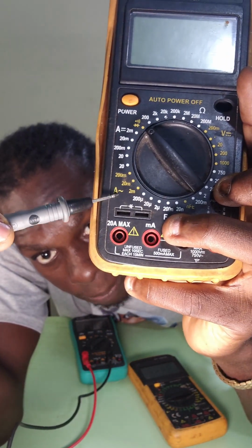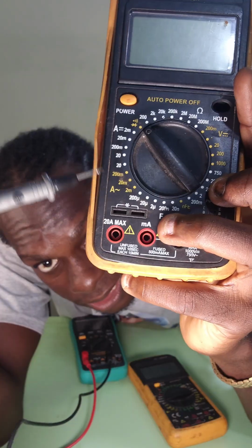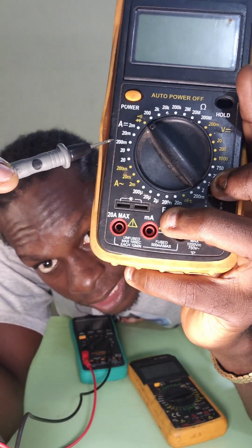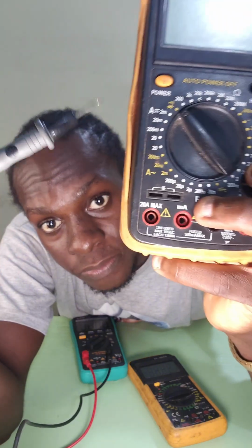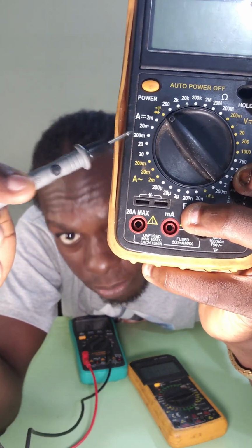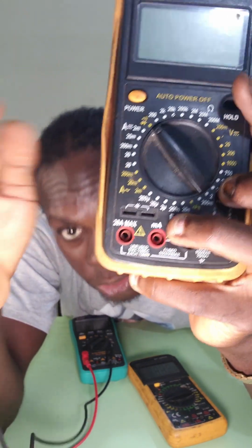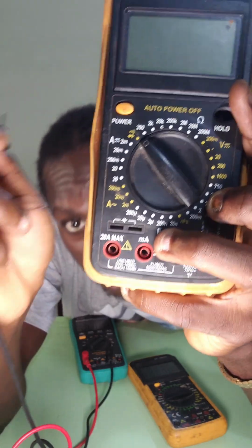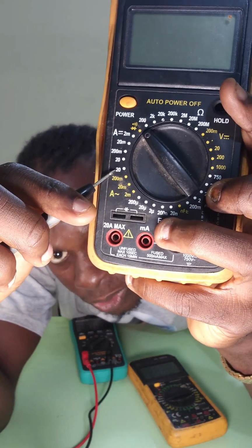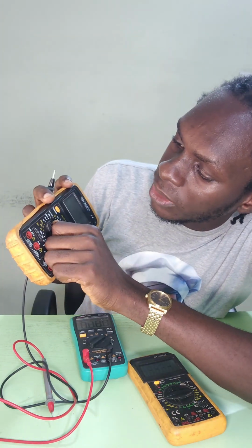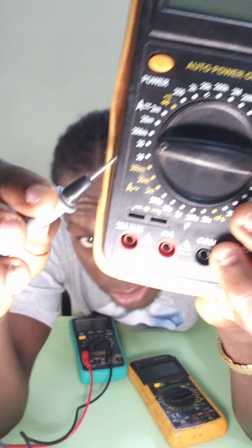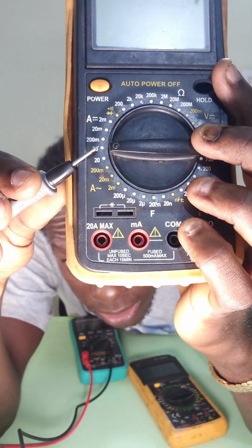So we'll have the yellow part for AC. You can see the symbol here, ACA, which is ammeter. And you have another ammeter for the DC. You can see the ranges. So depending on how much current you are to measure, you put it on that position. So let's say we are unaware of the current, you can always put it to the highest one. Now we want to measure DC current, you switch it to the maximum, which is 20. So we are at 20 amps currently on this meter.